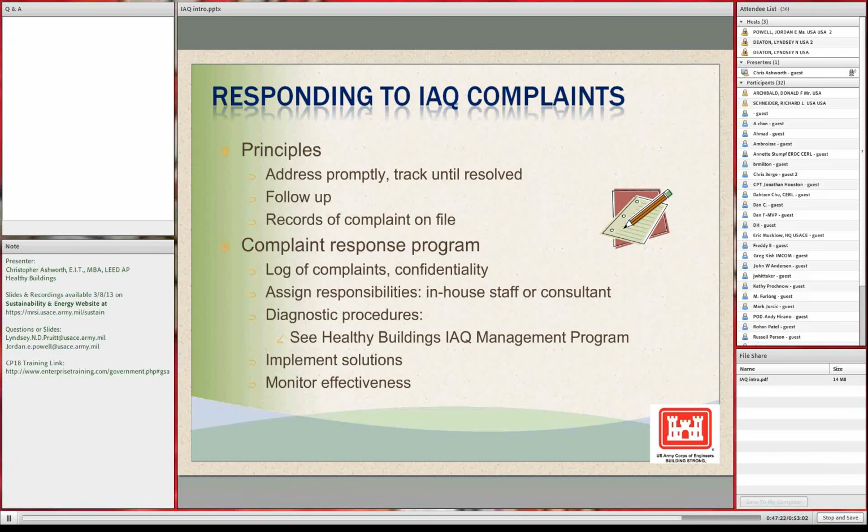With the piston effect with elevators, it's a difficult thing. Some of it cannot be prevented that I know of from a system approach, mainly because you do have these moving through the buildings. The biggest thing I think when you're looking at it is the activities going on in certain locations. If you have a laboratory or you have a print shop, which is very common, print shops producing tons of dust a lot of times, using various chemicals, you want to have those under proper pressurization to other